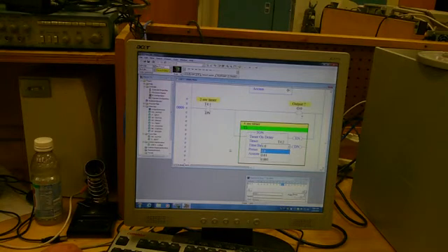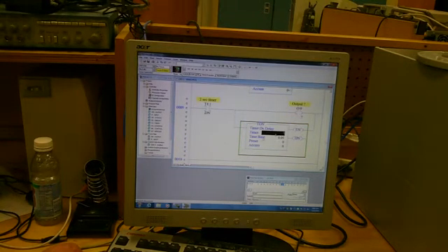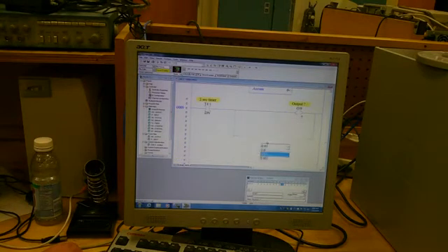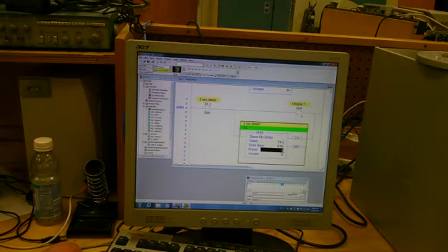So this is a 4 second timer, and time base, we'll change the time base to 100, and we'll change it to 4. Darn, got the wrong one. T. Yep. Right, that's the one we want. No, that's not the one we want. Yeah, that's one. Okay, everything's fine. All right, now we're here, 400. Now we have a 4 second timer.